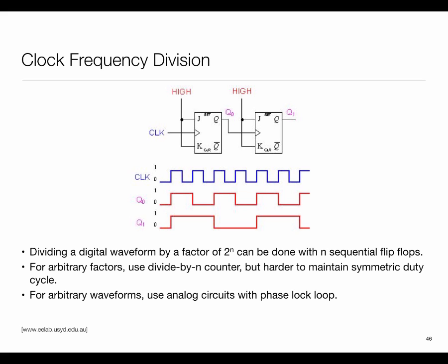So I have a high frequency clock. From that, I can derive lower frequency clocks as long as they are well-behaved, in terms of being divided by some integer value, for example. But when it comes to getting more complicated frequencies, like if I need a higher frequency than my clock, or a very odd multiplication, like 2/3 of the frequency, then you begin to need a more sophisticated circuit.